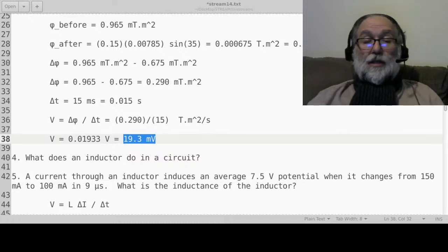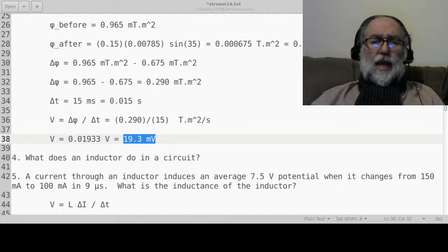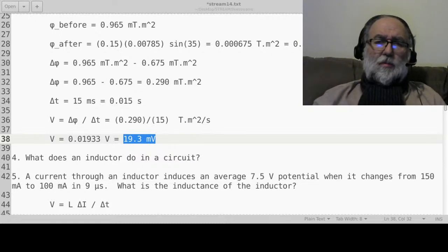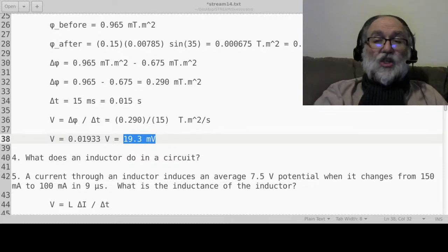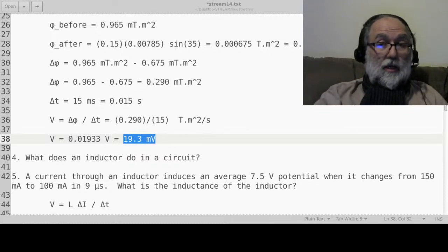And then there is an inductor, and the inductor is probably the hardest of them to understand. So if you've got a circuit and there's a current moving through the circuit, if there's no resistance, that's like no friction. The current will just keep moving at the same speed, okay? What an inductor does is, because it's like a solenoid, it builds up a magnetic field which keeps that current going. And if you try to stop or start the current, like if you try to increase the current or decrease the current, it resists changes in the current.